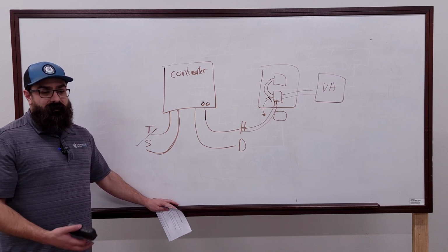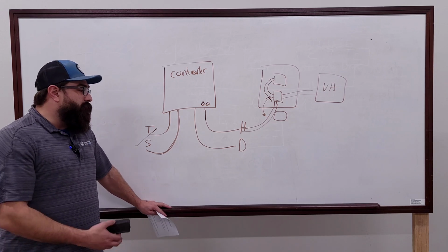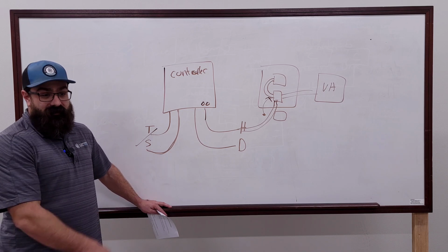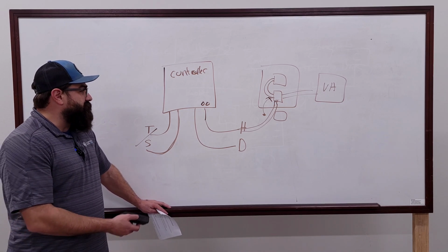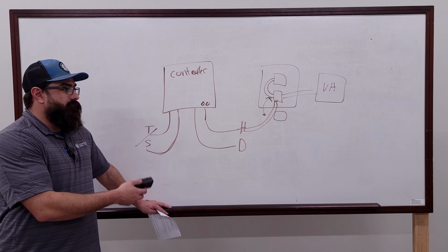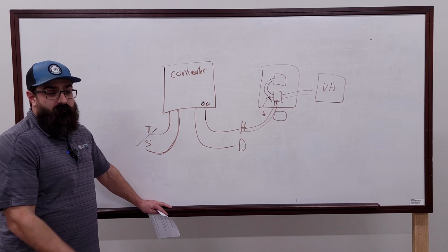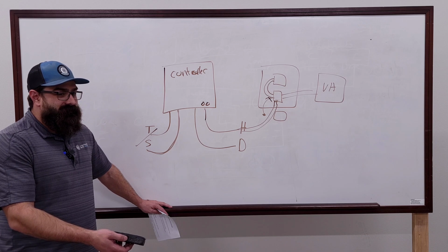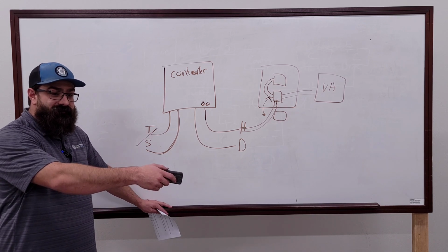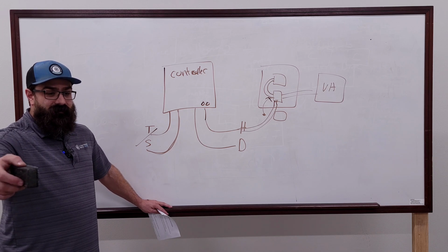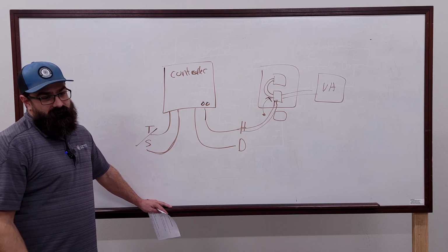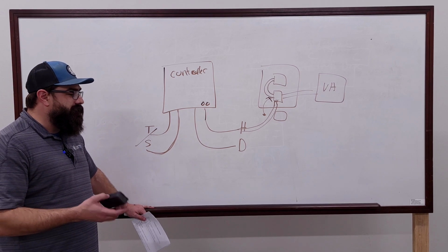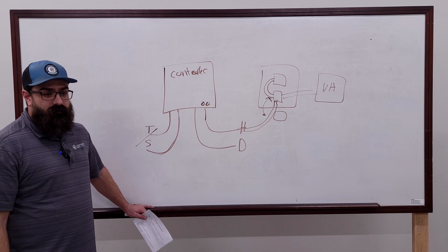Some we can't, and in that case, I would sit on the phone and try and help you figure it out. But yes, in theory, you could test all the other outputs and look, but if the output's configured wrong, like it could have been, originally that box was a staged heat, and they replaced the box in a TI, but they didn't reprogram the controller. Happens all the time. And now you've got a controller that's putting out 24 volts for an output that's wired up to an SCR. It doesn't do anything. So there's so many things that can go wrong that you need a little bit more information to know, right? You know what I mean?